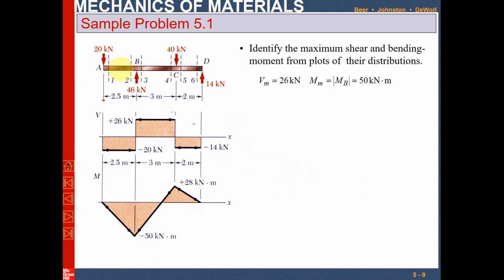Again, this is the beam and these are the sections shown and the reaction forces are shown. You have to draw two vertical lines from the ends of the beam in order to draw the shear force and bending moment diagram. First we will draw the shear force. Between these two lines you have to draw a horizontal line which shows the length across the beam.